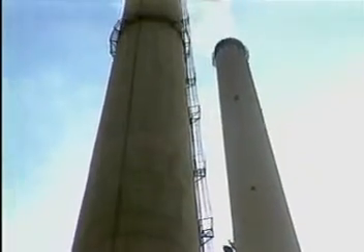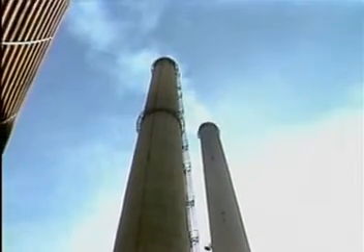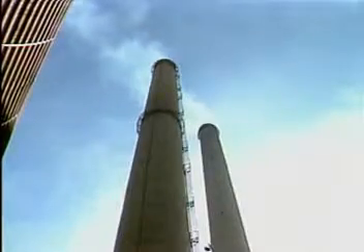To protect the environment, the gases are treated to remove harmful substances before the combustion gases are discharged. Three commonly used devices for removing harmful byproducts from combustion gases are scrubbers, electrostatic precipitators, and bag houses. Some scrubbers can remove both particulates and gases, while precipitators and bag houses remove only particulates. Let's take a look at how each device operates.